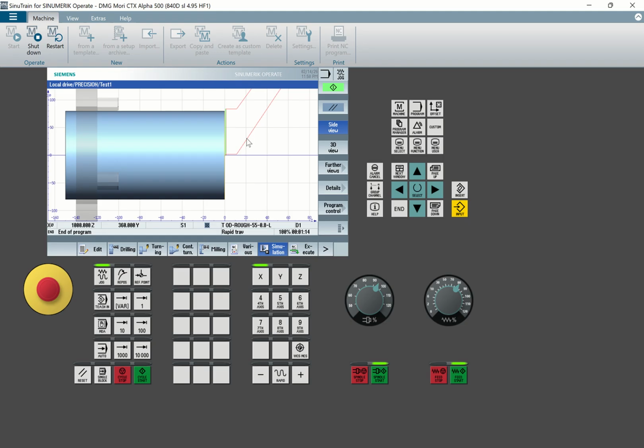You see, for ISO code we put the points, point to point. Same way it can happen here, but because it's ShopTurn, let's go to contour. I want to go to contour. Also you can use a normal way, straight turn, or a G code. For example, you can use a G code, but this you use ShopTurn first of all, then I'll show you how to use a G code.